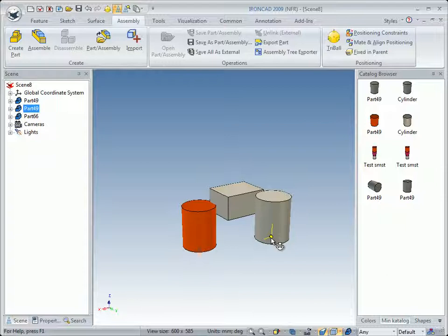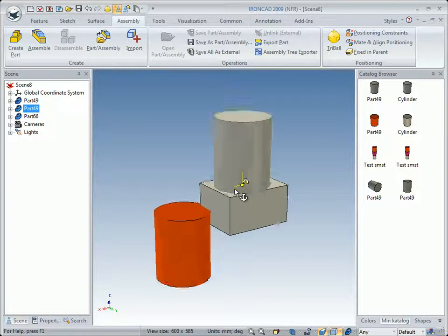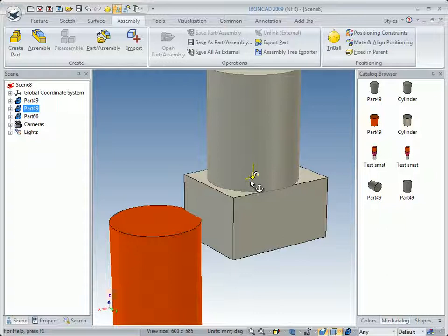But if you change that, select the anchor and right click and select drag along surfaces, now it will snap to surface and face on every part you have in the scene. And if you press the shift key and left drag the part, you will snap to edges, midpoints, and so on. And that's another way to move a part in the scene.